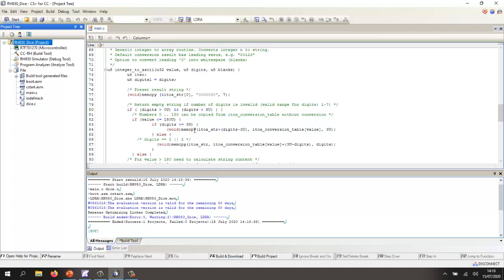I'd also like to execute the code on the simulator, and as it executes, find out how much of this code we have actually exercised. We probably won't get 100% coverage, and so I then want to do some unit testing where I can give it the appropriate values so it exercises the rest of the code.